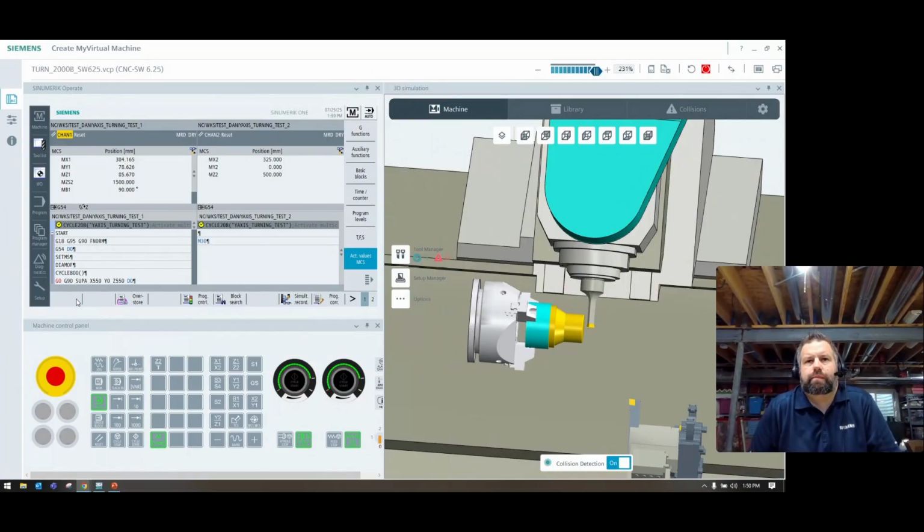Effectively from that side, we just want to make sure we program the feed rate accordingly. The only thing an OEM might need to be part of is that in that specific application, the main spindle is not spinning. Some OEMs don't allow you to program a feed if the spindle's not spinning.